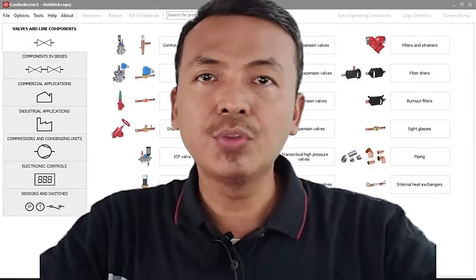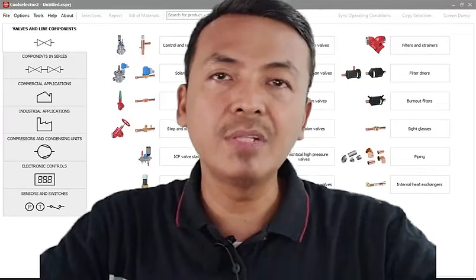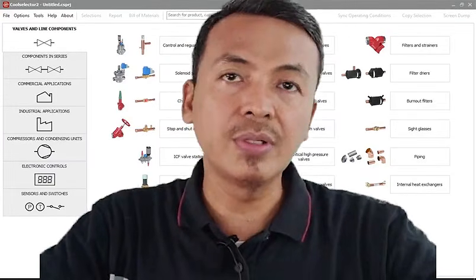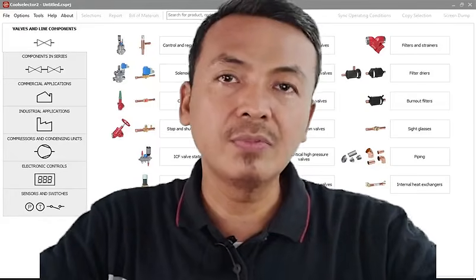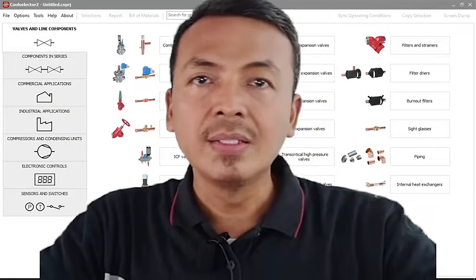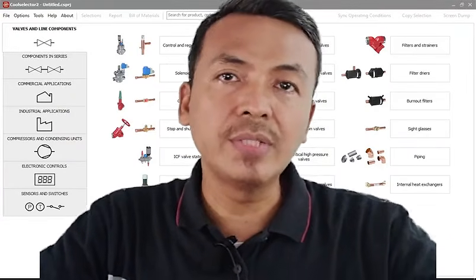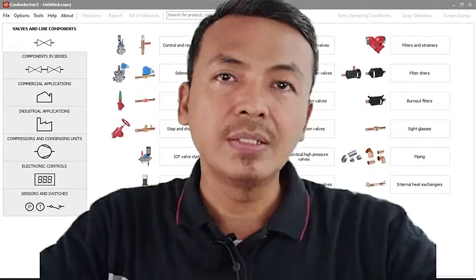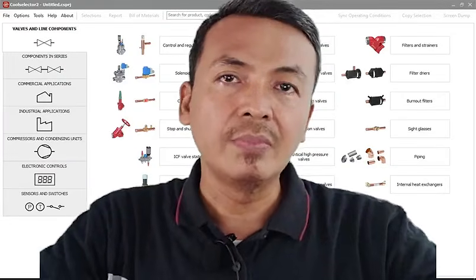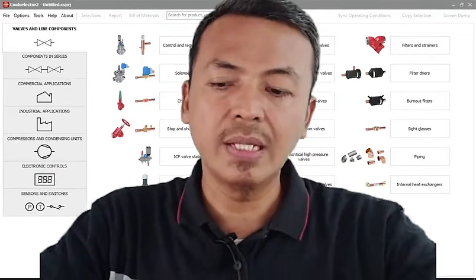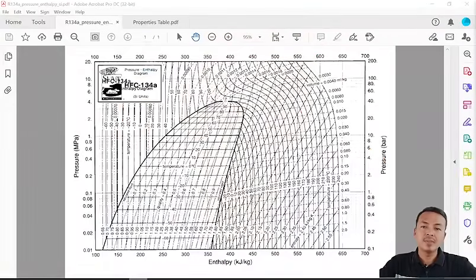In this video, I will show you how to determine the enthalpy values of the refrigerant for its process in the vapor compression refrigeration system. There are many ways to get the enthalpy value, such as using the pH chart or log pH chart, like this one. You can get the enthalpy value for each process after the evaporation, compression, condensation, and expansion.